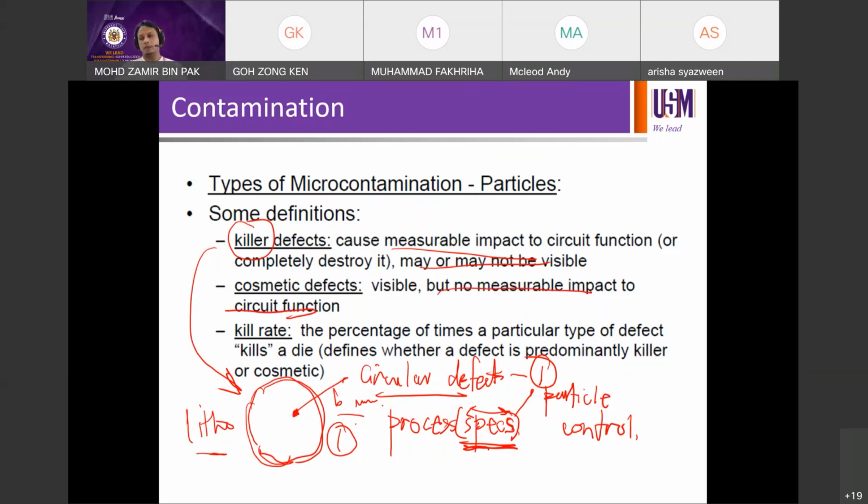So in this case, you need to scan for how many defects you have on the wafers, and whether or not you have them on other wafers as well. And see whether they are above the count or below the count that's spelled out in the specs. Okay, certain cosmetic defects you can probably tolerate, say hundreds of defects or 50 or 10. It really depends on what sort of defects.